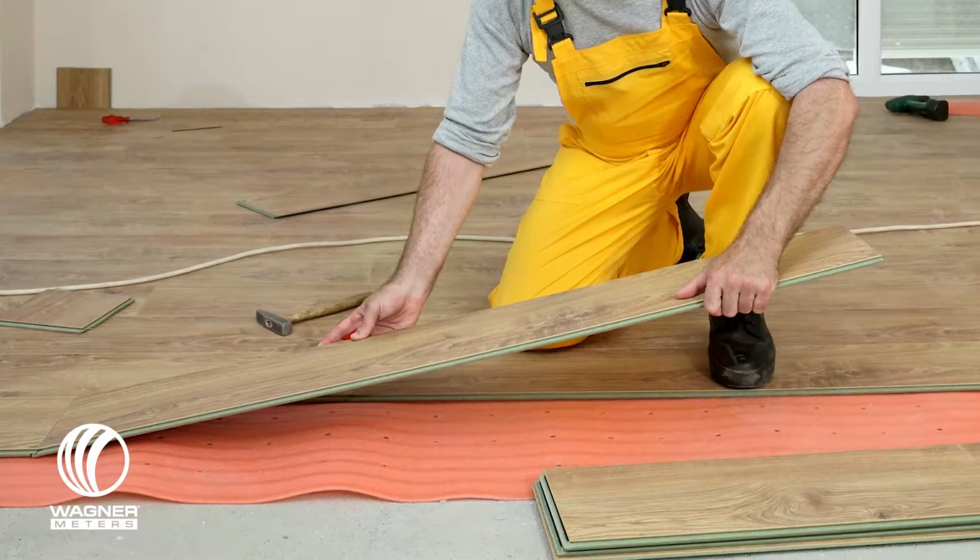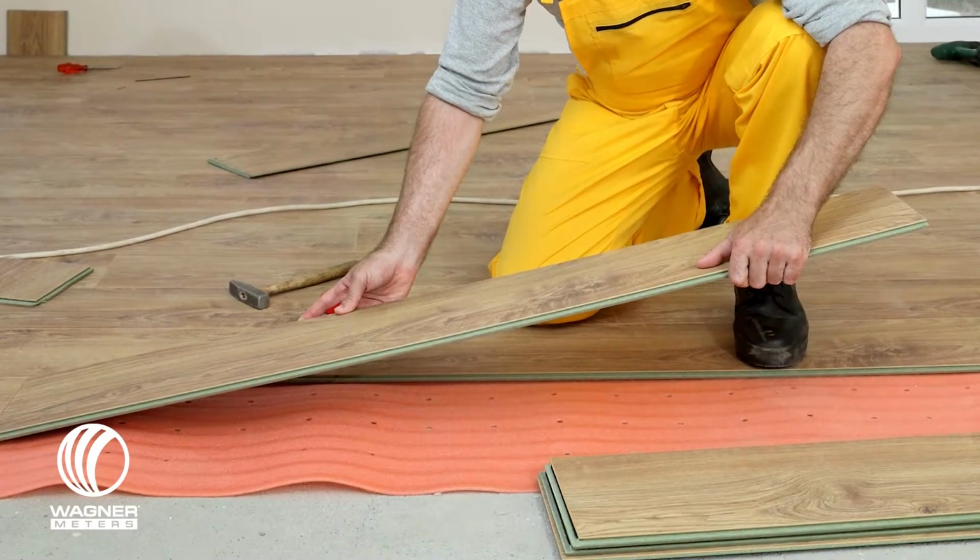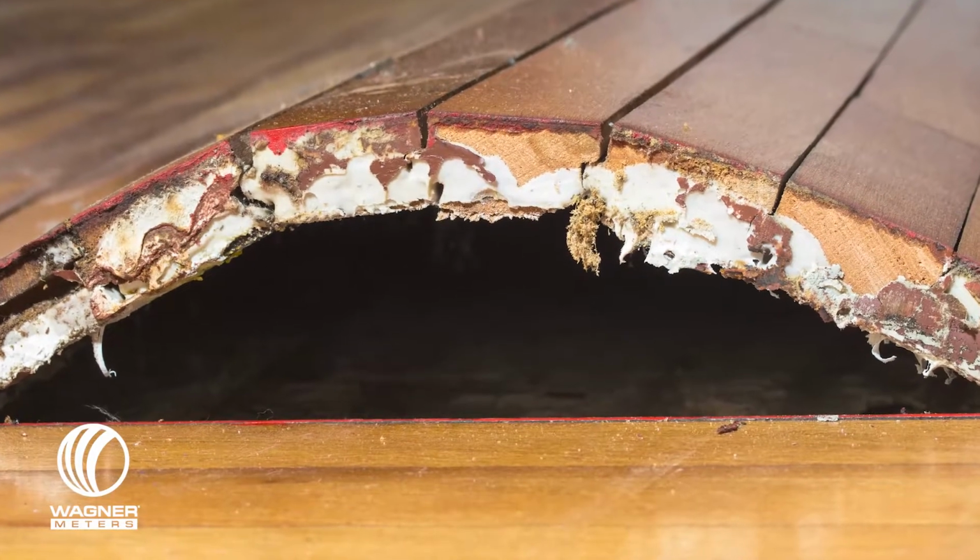Number two, floating floors. Floating floors are often recommended where moisture risks are high, but because of the risk, you'll need a vapor retarder between the subfloor and the flooring. However, if the retarder is compromised in any way, moisture from the slab can still damage the flooring or the finish. Something else to think about: this moisture may not impact the flooring, but will mold or mildew grow because of the moisture that is still present under the vapor retarder?